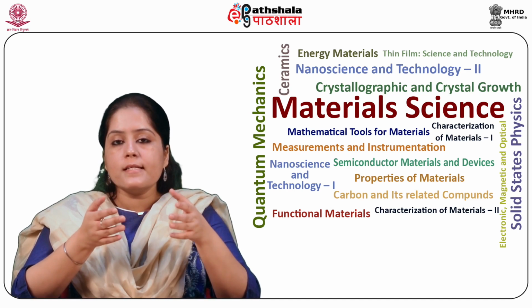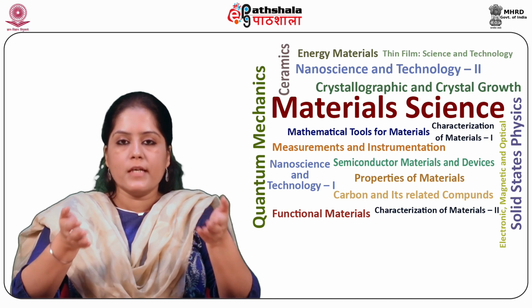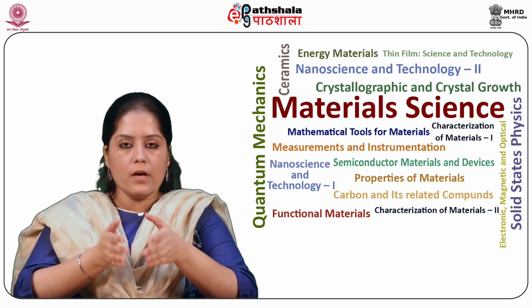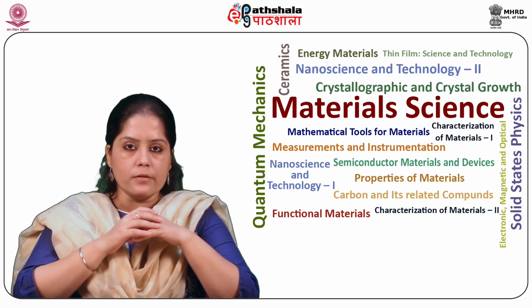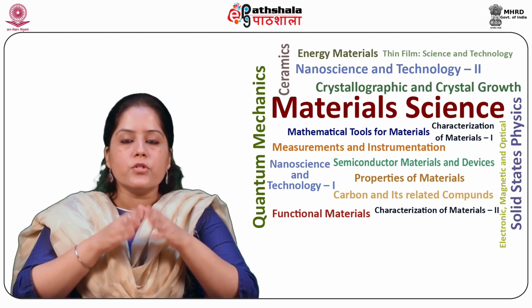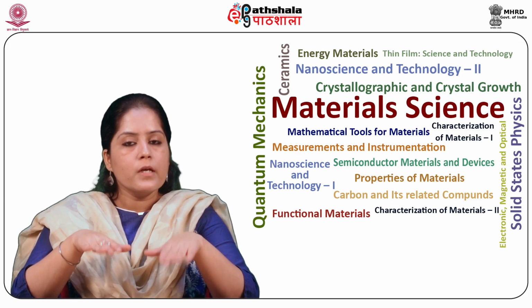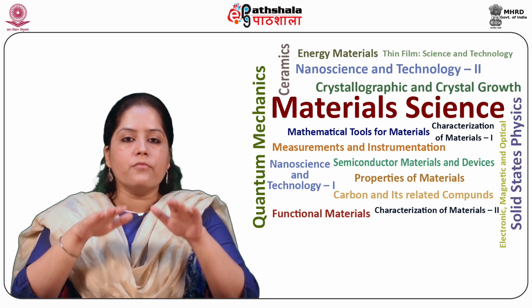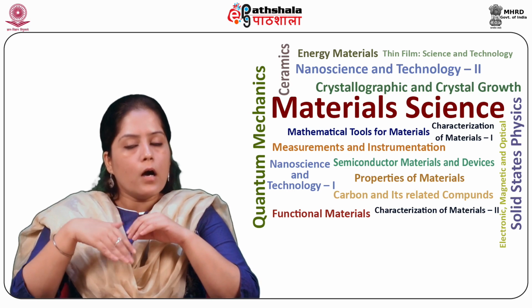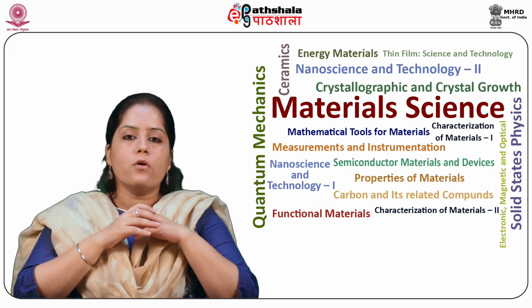So, next is the oxidation method. Different oxidation techniques lead to different ambient environments for oxidation. So, as mentioned above, while only dry oxygen leads to a slow rate, using hydrogen in the wet oxidation technique or chlorine along with the oxygen increases the rate of oxidation.